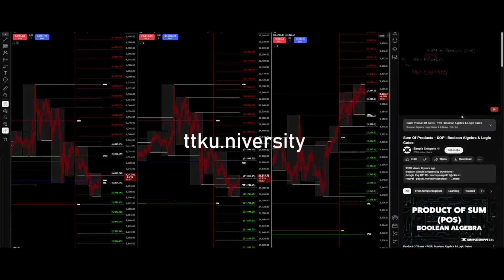Okay, so now that you've understood the sum of products expression, let's see what a standard sum of product expression means. So far you've seen the SOP expressions in which some of the product terms do not contain all of the variables in the domain of the expression. That is, check out this case. Here in this product term, we are missing the variable C, and in this product term, we are missing the variable A. So this is a sum of product expression, but it is not a standard sum of product expression.